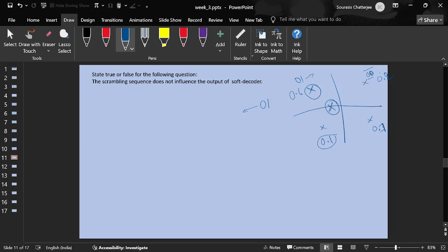Hard decoding is all about making a confident detection at the demodulation stage. So even if there is error, that error will propagate. And soft decoding is about calculating the probabilities and feeding those probabilities to the LDPC decoder. I have calculated the probabilities. You see now, these are the probabilities that this received symbol can be these symbols, and there you will have this likelihood. You take the log of that and take the ratio, and if it crosses a certain threshold, you make the decision. But that's up to the LDPC decoder, not at the demodulation stage.